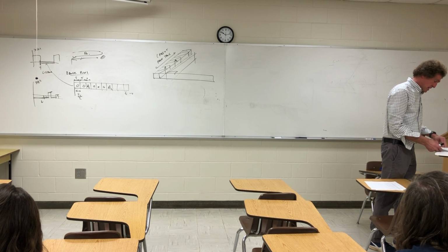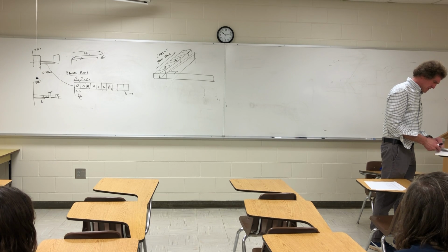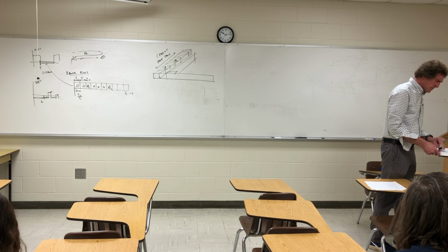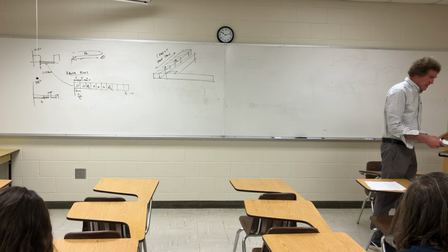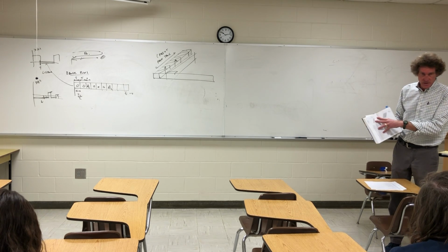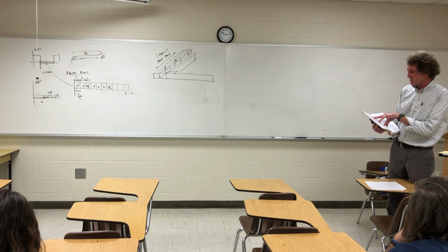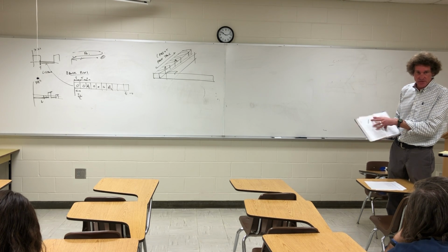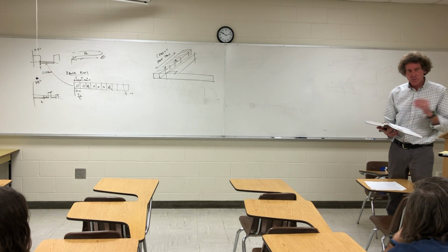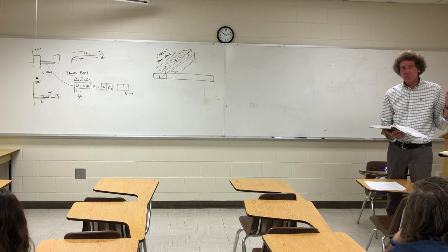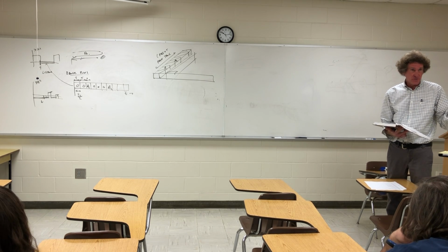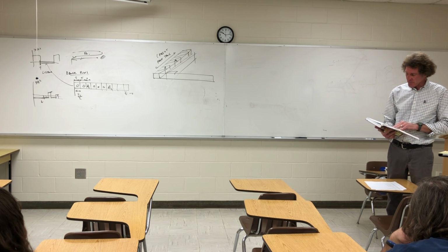Look at my range bins, figure 8.13. Okay, here's what I'm talking about. The way they're doing it, there is the one on page 290 where it shows a single range bin. It's just storing information, and each one of those things is a width tau. Now, actually, normally they sample at least 1/2 tau, just to make sure that they don't miss the target, or faster, and they store them in range bins.